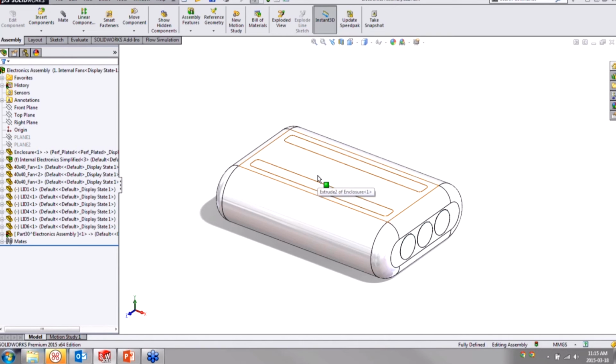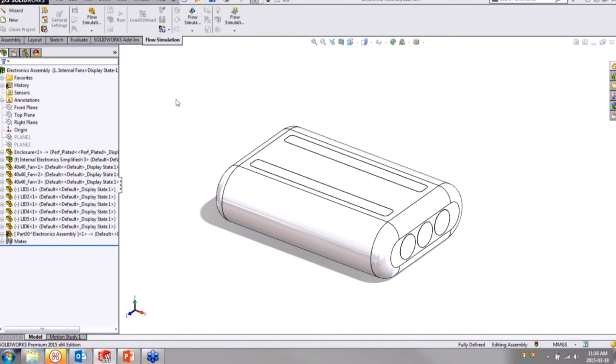Obviously, creating the lids manually is a little bit more work up front. However, this is typically the way that I like to do it. And the main reason is because I now have lids which are parametrically linked to the model. The limitation of the Create Lids tool is that it creates non-parametric lids which aren't fixed in space. So you can run into a bunch of problems here.